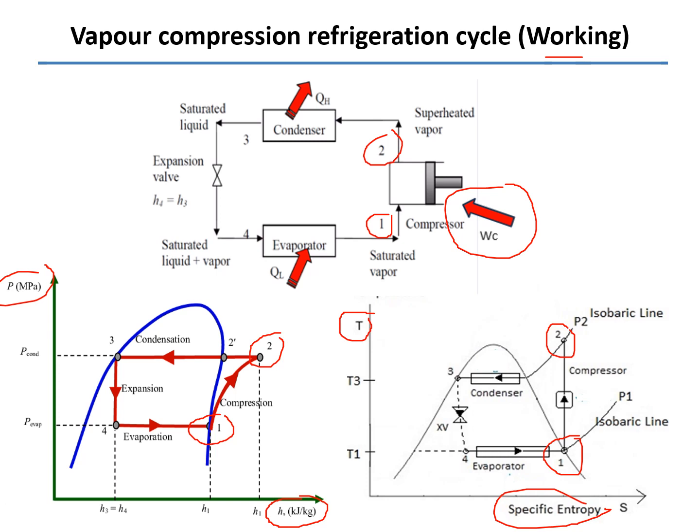So the compressor is doing the conversion of the electrical energy into mechanical energy, and that mechanical energy is used to compress the refrigerant, and definitely the state will change from 1 to 2, and then 2 to 3. That process is in the condenser, where the heat rejection takes place.